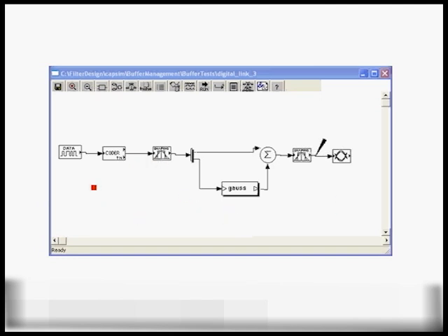So let's go over this one more time. Each source block, for example, let's take this data block here that can potentially generate a gigabit worth of data, every time it is visited actually generates only, for example, 128 bits, a chunk of bits. Those bits go through the pipeline and are processed by the other blocks in order to generate results. And once all those samples have been consumed, the kernel revisits the source block and generates another chunk of data. That chunk of data is processed and consumed by the other blocks, generating results again.